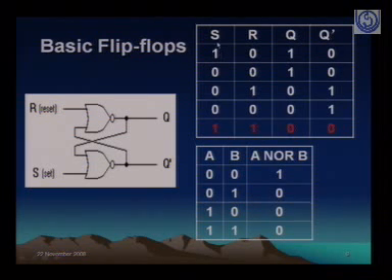So as soon as you applied S as 1, what is the result? The flip-flop is in set state. Now the flip-flop will remain in set state even if we move S to 0. Let's try that situation. Now S moves to 0. R was already 0, so that is fine. So the flip-flop should remain in the set state. Then only we can be assured that this flip-flop is still in set state, maintaining the state. In other words, it has become a storage element and it is remembering 1.